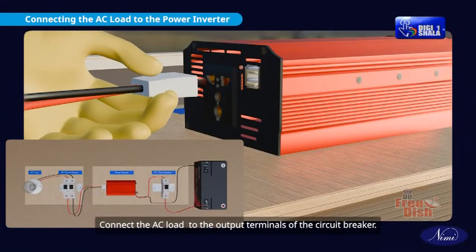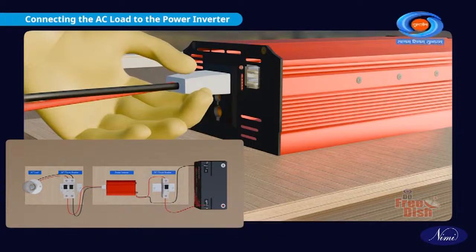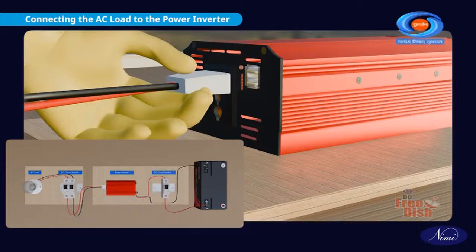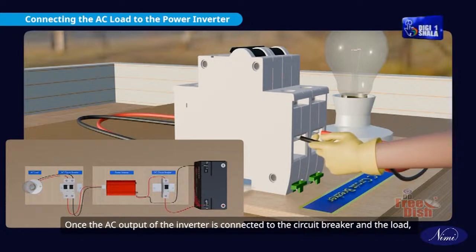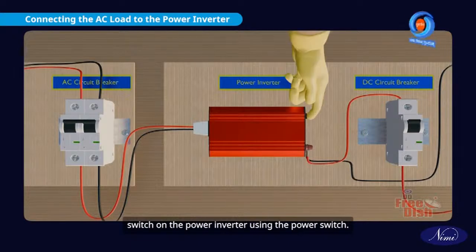Connect the AC load to the output terminals of the circuit breaker. This can be done using standard AC cables terminated with appropriate connectors. Make sure that the load connections are secure and properly insulated. Once the AC output of the inverter is connected to the circuit breaker and the load, switch on the power inverter using the power switch.